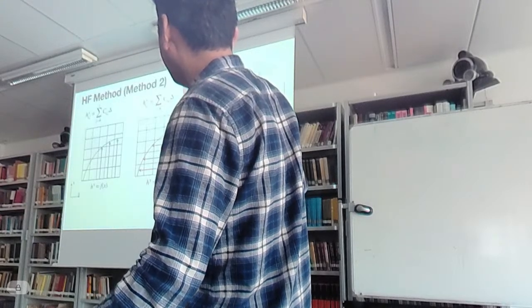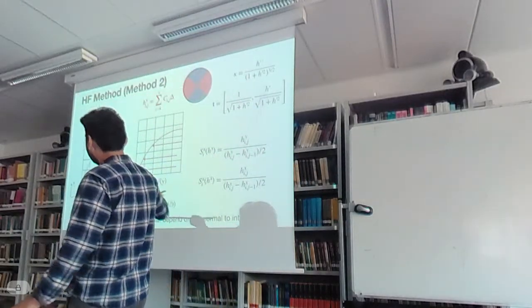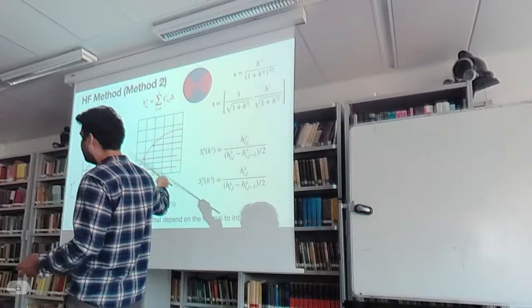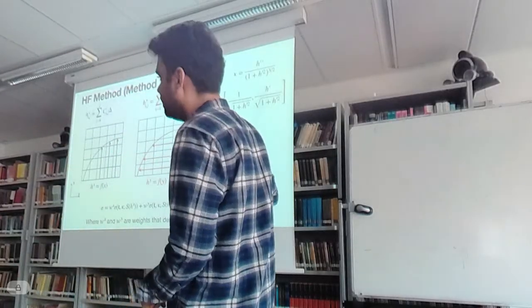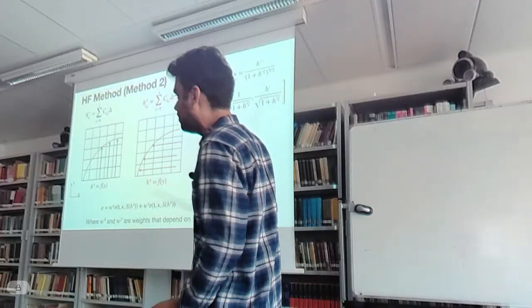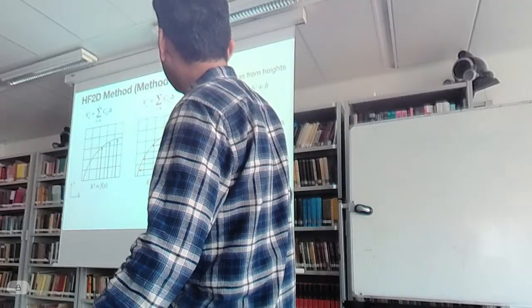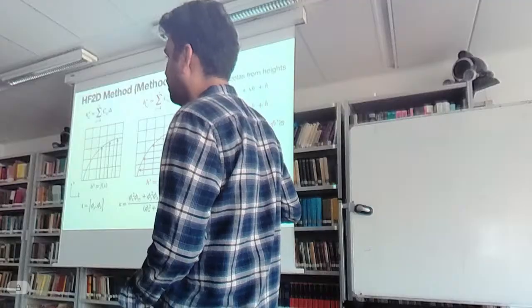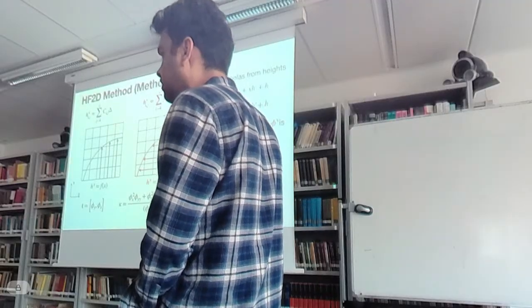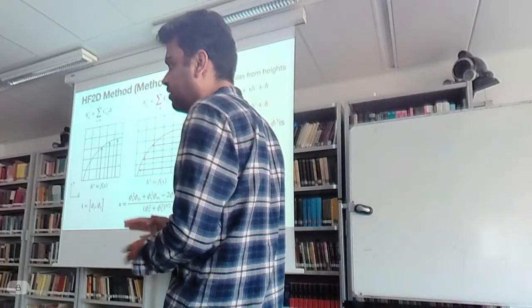The reason I weight here is that if I don't weight, and use either or, this is already much worse and I have many more oscillations. So this is the height function, right? And when you have HF2D, you somehow do better averaging of the two, which was the main source of oscillations, in my opinion, when I use only the height function method.